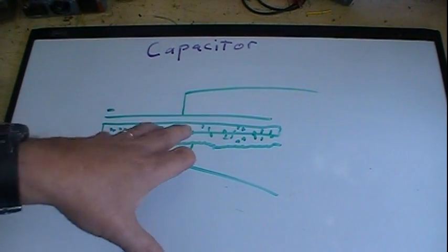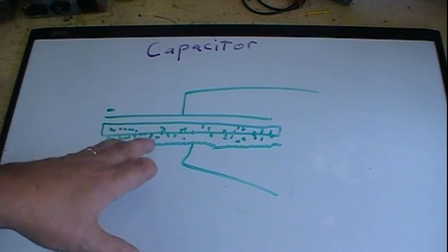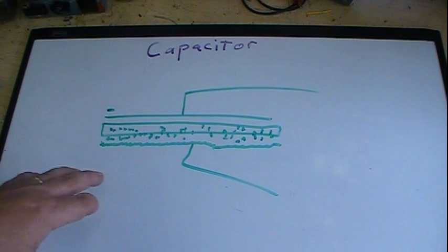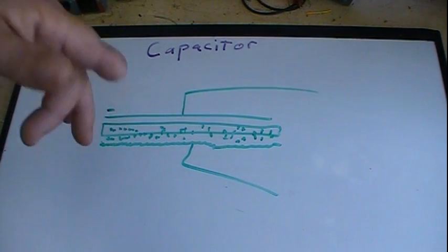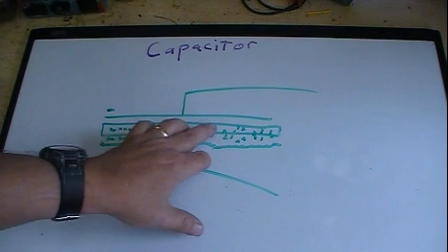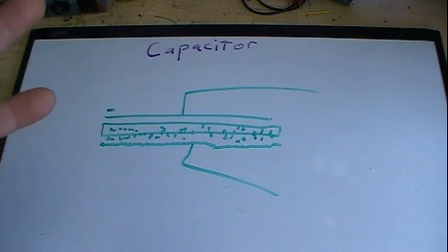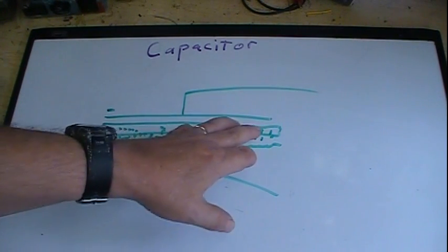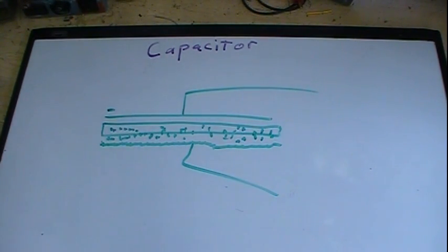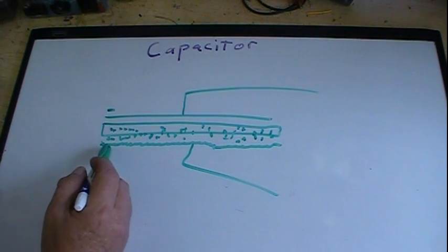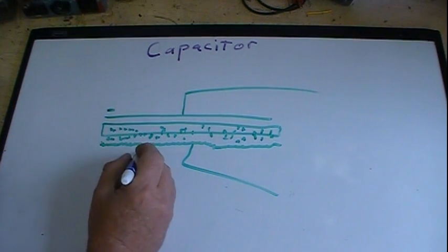And then there's the dry electrolytics, which from at least the mid-30s on is the most common and used, and it's a paste. It's the same stuff, but then they add other ingredients to turn it into a paste, and they get it basically pushed into the dielectric insulator, but it does interact directly, for all practical purposes, with this positive plate.